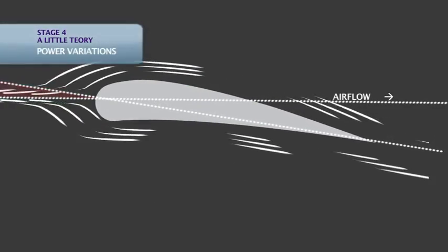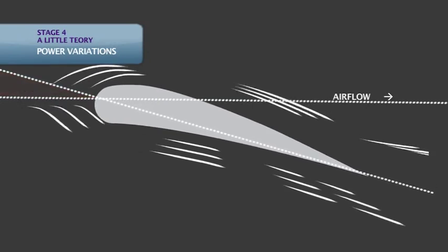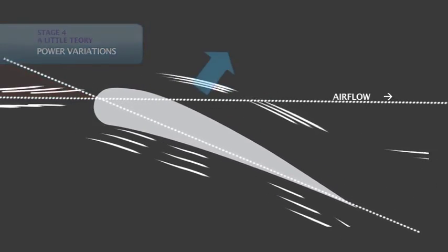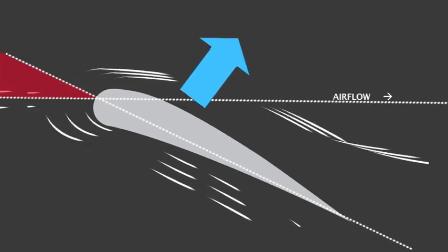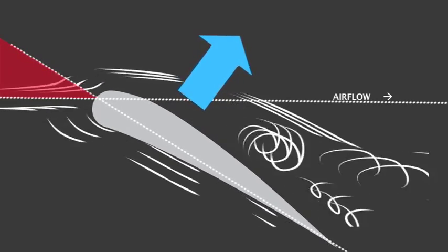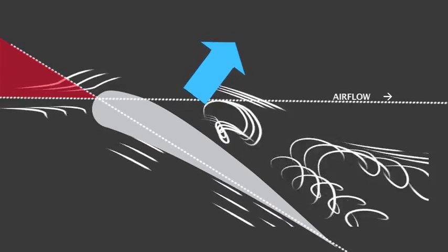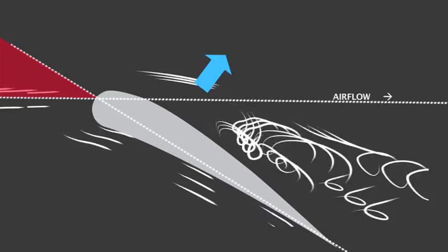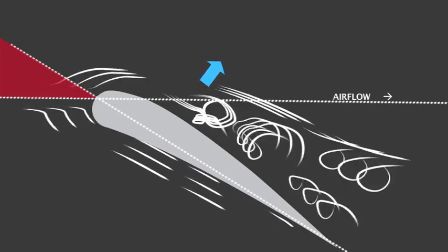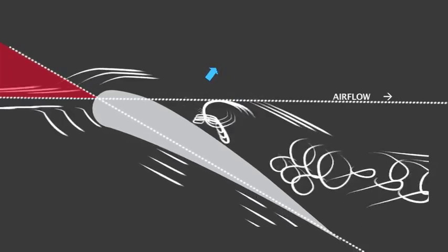What changes the traction force of the kite? The power of the kite may increase if the wind rises or if you accelerate the kite in the wind window. A higher angle of attack will also increase the traction. However, if the angle of attack exceeds a certain value, then the turbulence created by the profile will increase and directly reduce the flight ability of the kite.